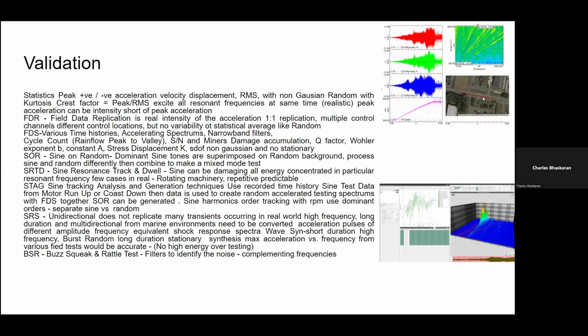In the lower right-hand picture, the track is where a run-up is happening. The red curve is showing you the X, the green is showing you the Y, and the blue is showing you the Z. The spectrum is shown where the run-ups happen, and you can see all the frequencies, which we call orders. Those different orders can be understood based on the product.